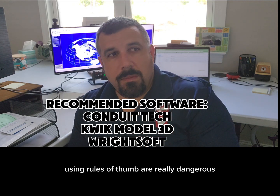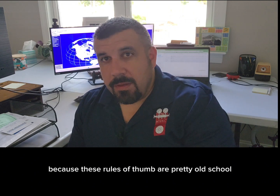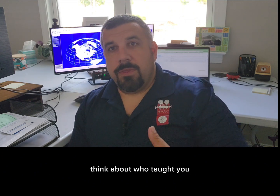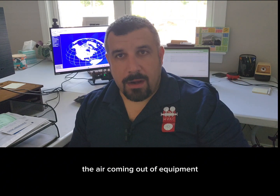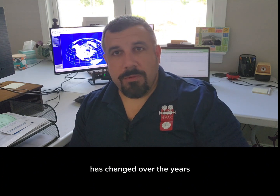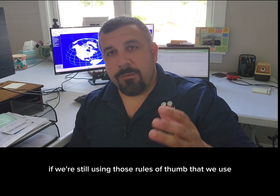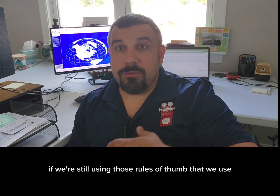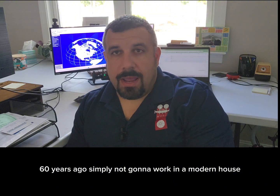Using rules of thumb are really dangerous, especially because these rules of thumb are pretty old school. Think about who taught you, maybe who taught them those rules of thumb. Equipment has changed, the temperature of the air coming out of equipment has changed over the years, houses have changed, there's all these moving targets. If we're still using those rules of thumb that we used 30, 40, 60 years ago, they're simply not going to work in a modern house a lot of the time.